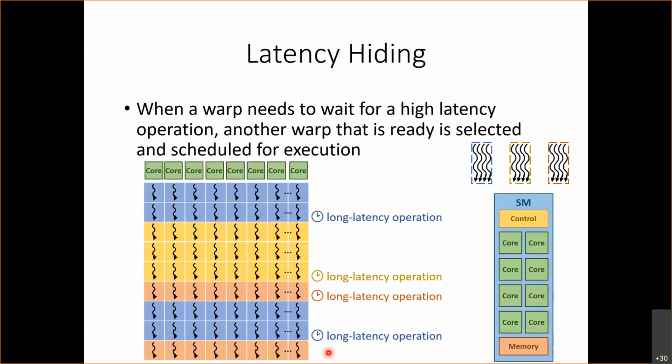So if you want your processor to have low latency, you optimize how long operations take. But if you want your processor to have high throughput, then what you do is you have a lot of cores, even though these cores have longer latency, and you tolerate that latency, or you hide that latency by having many threads executing together.